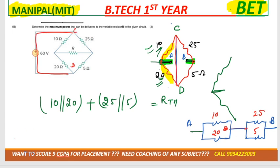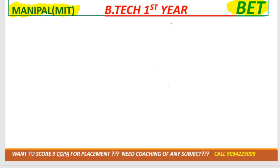So basically they are asking the power, right? So power formula is P max is V square TH divided by 4 RTH. So VTH also you calculated, RTH also you calculated. You need to just substitute the values. Correct?